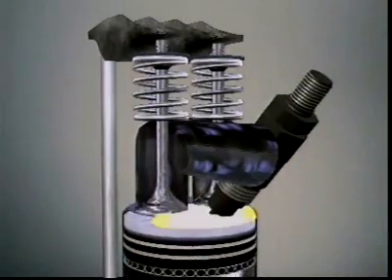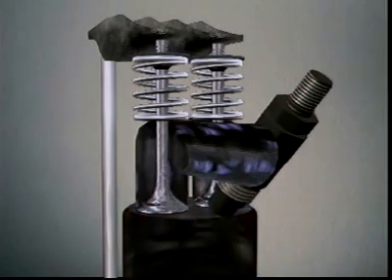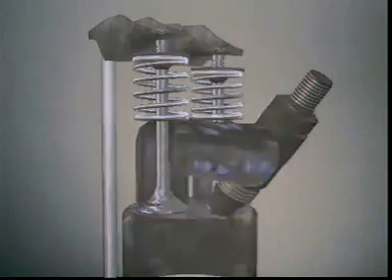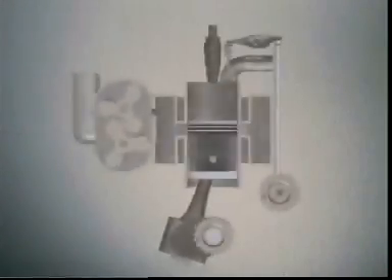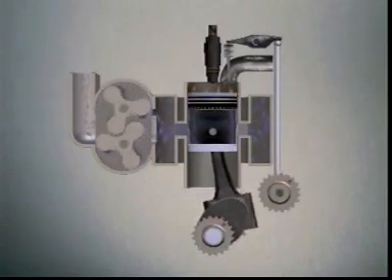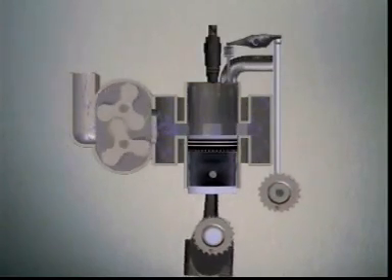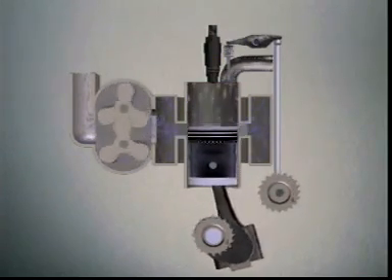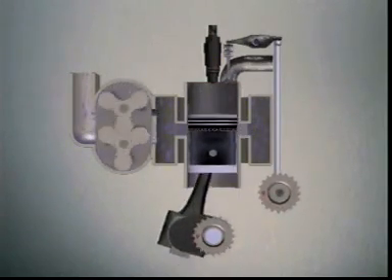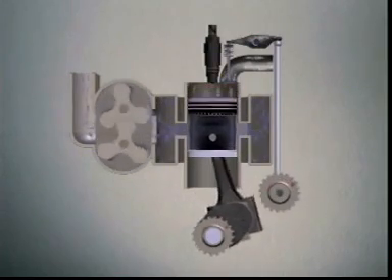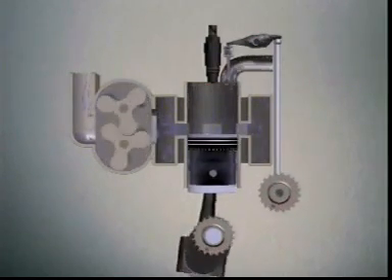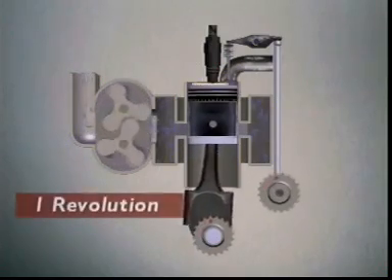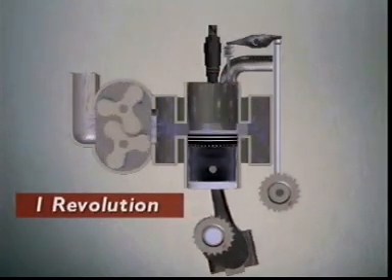In the four-stroke, the valves must open only when the piston is in the correct position. The position of the piston is just as crucial in this two-stroke diesel engine. Its exhaust valve must open and close at the right point in the engine cycle. In one two-stroke engine cycle, the crankshaft makes one revolution.